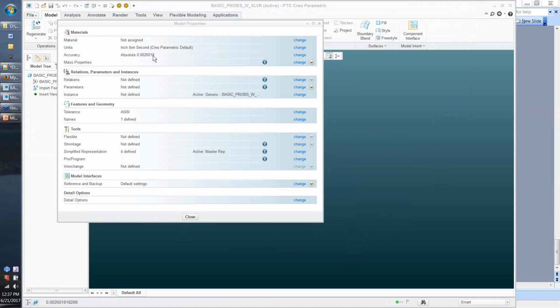I can either make the tooling equivalent to that, or I can suffer terribly by trying to make better tooling than my reference part. That typically is a very difficult workflow where you're going to encounter enormous problems inside the mold environment by trying to create features using the reference part at an accuracy that the reference part doesn't even have. So that's how I handle it. That's how I speak to it.